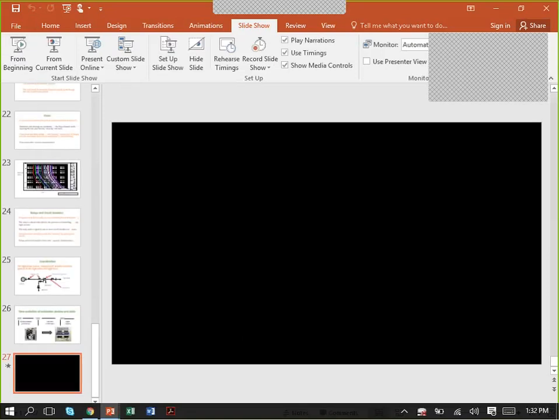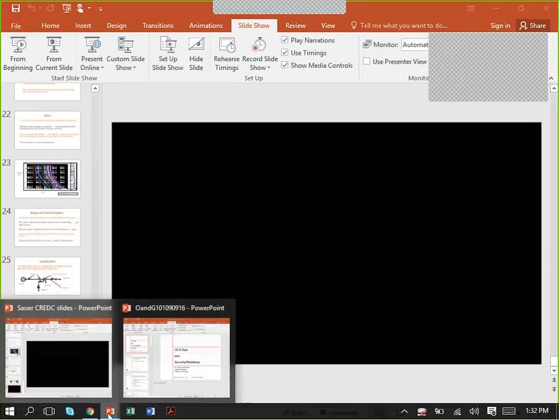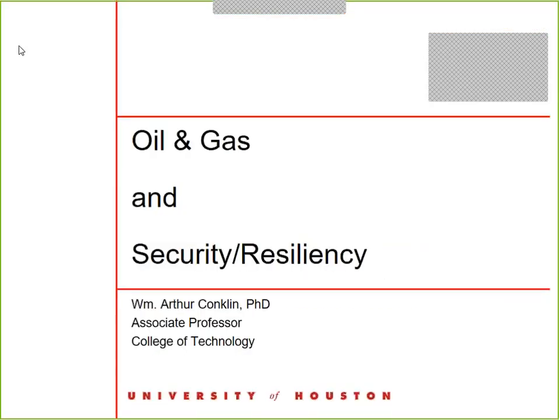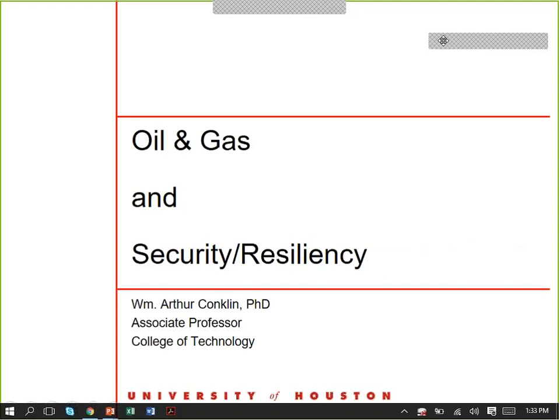Very quickly, as we're introducing Art, Pete did touch on something that you may not have noticed as it went by, which is that we're interested in cybersecurity and resiliency, and where possible, we like to involve the physics. So, for example, I'm very aware of the project that Pete spoke of, where we're observing the network traffic, the commands to and from the relays, the communication between the relays, and we're reconciling it with measurements and saying, does Kirchhoff's law hold? And if not, one of those relays is lying. So this is where you can take the cyber and the underlying physical model and make it work.